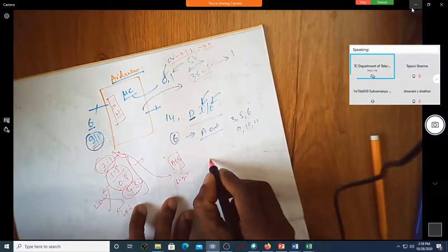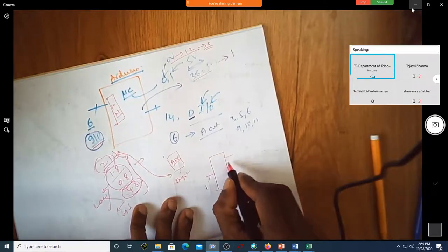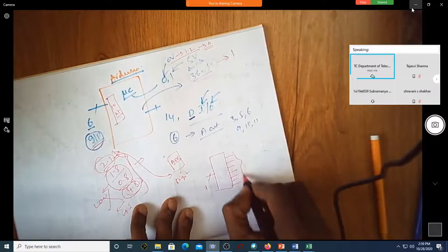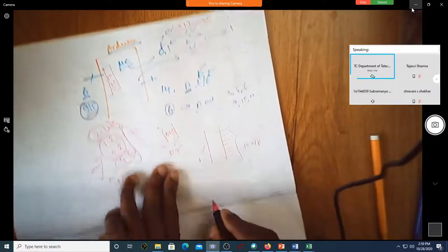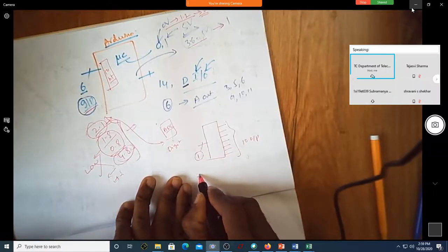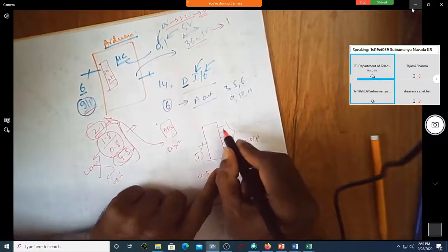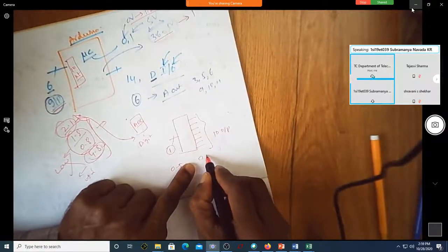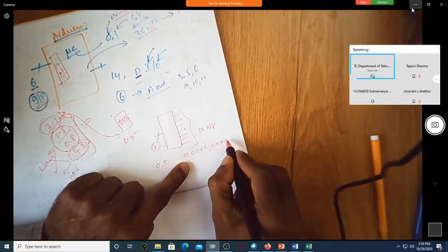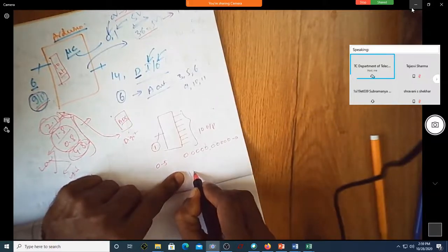It is going to have one analog input and 10 digital outputs. So it has 10 output pins, meaning the analog input can change from 0 to 5 volt. The digital output has 10 bits. This is one extreme, the other extreme is all ones.